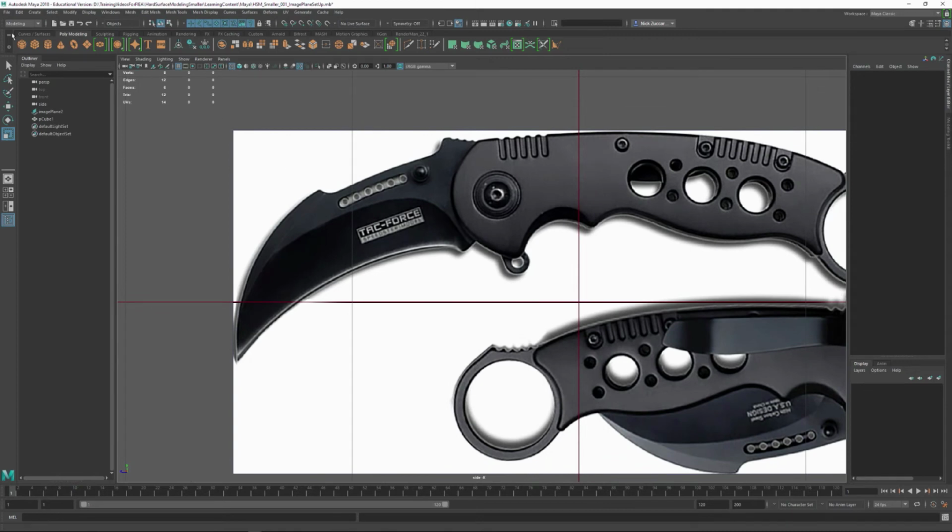So I'm going to go into the Modeling subset and go to Mesh Tools and say Create Polygon Tool, and I'm just going to click. I'm just going to go like this. This is going to be a really rough shape, just so we know that we can get objects outside of the program.